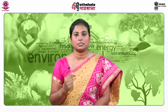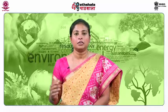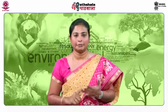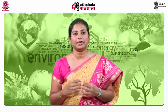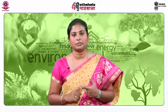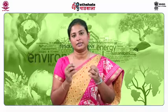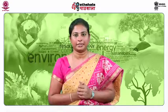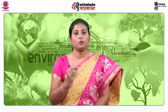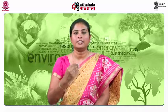An ideal gas collection system consists of a sequence of gas collection wells which are positioned throughout the landfill. The gas collection wells are designed based on the volume and density of waste, and the depth and area of the landfill. Collection wells in the landfill offer pathways for the passage of gas. The gas collection system is very important because if it does not work properly, an explosion can occur within the bioreactor. You can also see more gas generation in the early phase of operation. Moreover, compared to conventional landfills, landfill bioreactors generate a high amount of gas.